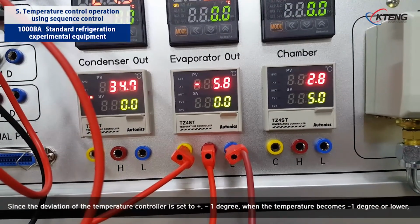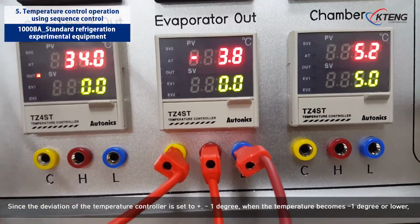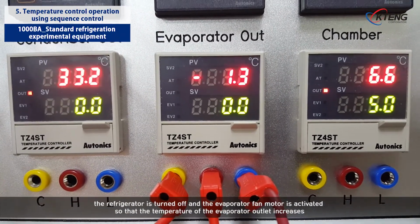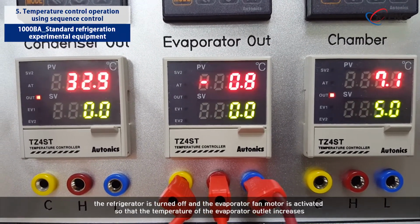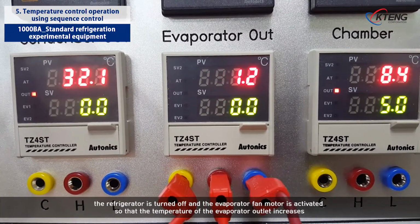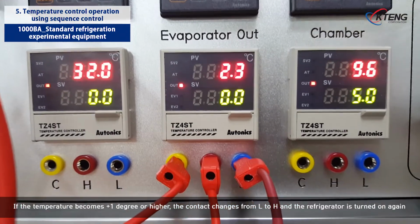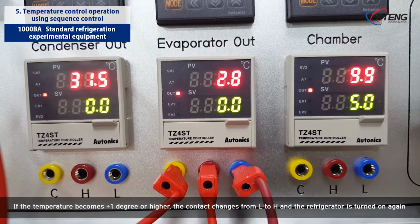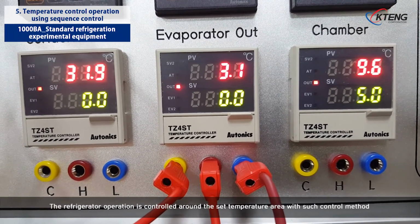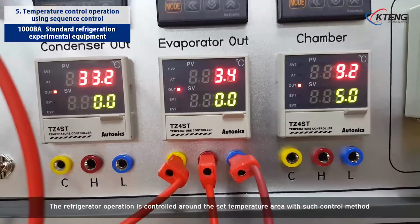Since the deviation of the temperature controller is set to plus-minus 1 degree, when the temperature becomes -1 degree or lower, the refrigerator is turned off and the evaporator fan motor is activated so that the temperature of the evaporator outlet increases. If the temperature becomes +1 degree or higher, the contact changes from L to H and the refrigerator is turned on again. The refrigerator operation is controlled around the set temperature area with such a control method.